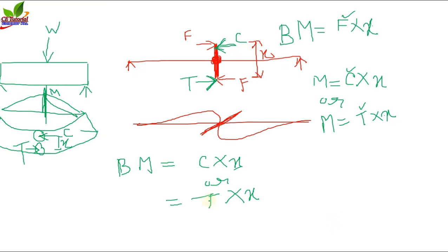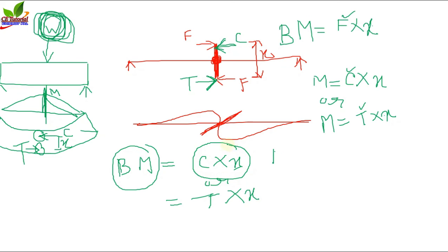So that means this beam can resist this amount of load W. What I have done is equate the external bending moment to the bending moment created by the material itself.